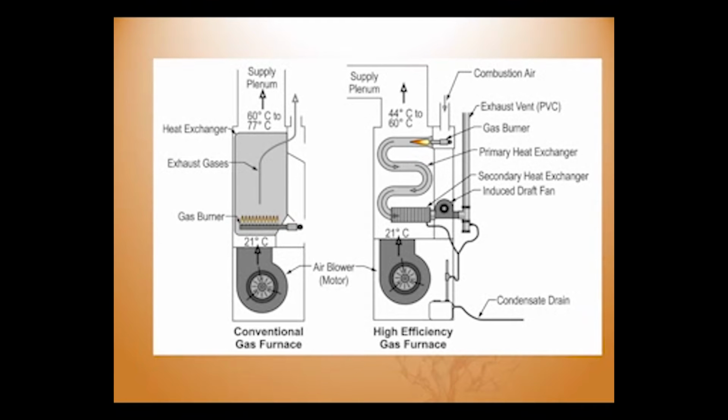High-efficiency units are built to recover and utilize as much of that lost heat as they can, and they do this by allowing the exhaust gases to cool inside the heat exchanger. The cooler combustion gases are now exhausted through a Schedule 40 PVC pipe instead of a steel pipe. Since the gases are so much cooler, convection no longer works. Therefore, we also need to add in an exhaust fan. We also need to be aware that the internal cooling will create internal condensation, which will need drainage.